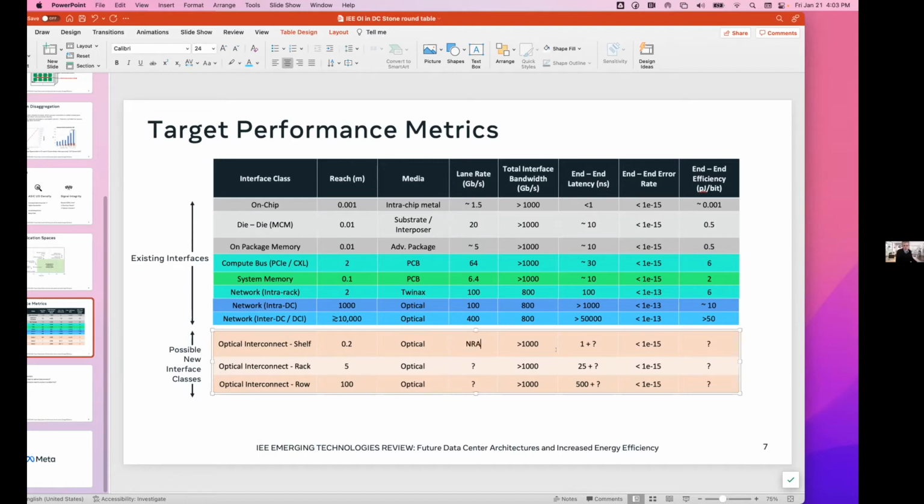Okay. Well, there's no reason in optics not to use NRZ forever, because the single mode channel is tens of terahertz of bandwidth. So it'll be a long time before you start getting into channel limitations like you do in copper. And assuming you keep advancing your packaging and your electronics so they don't limit you, you can just always crank the baud rate up. But then you get into the issues of ecosystem. If you're trying to have common SerDes with the copper channel, which is band limited, then you can't do that for the copper channel. So now you start having the copper modulation be different than the optical.